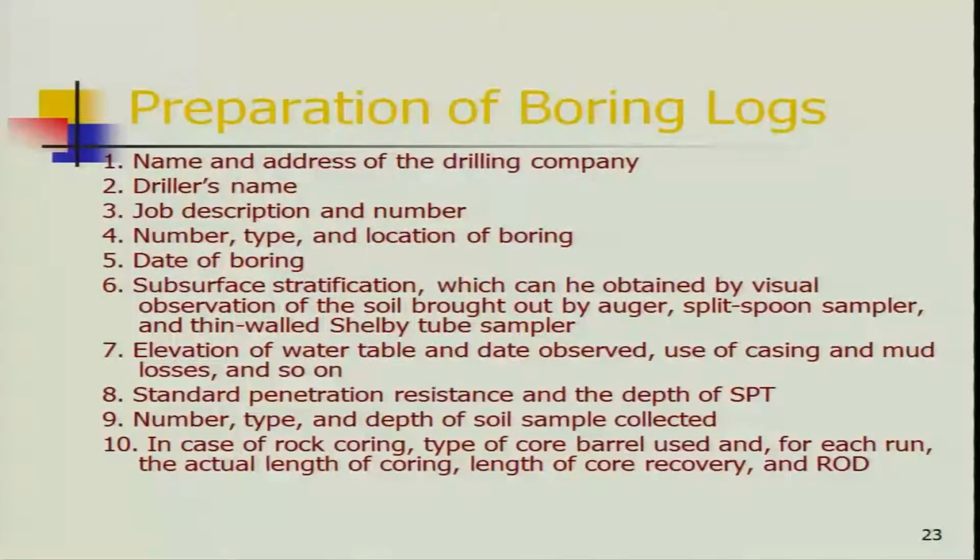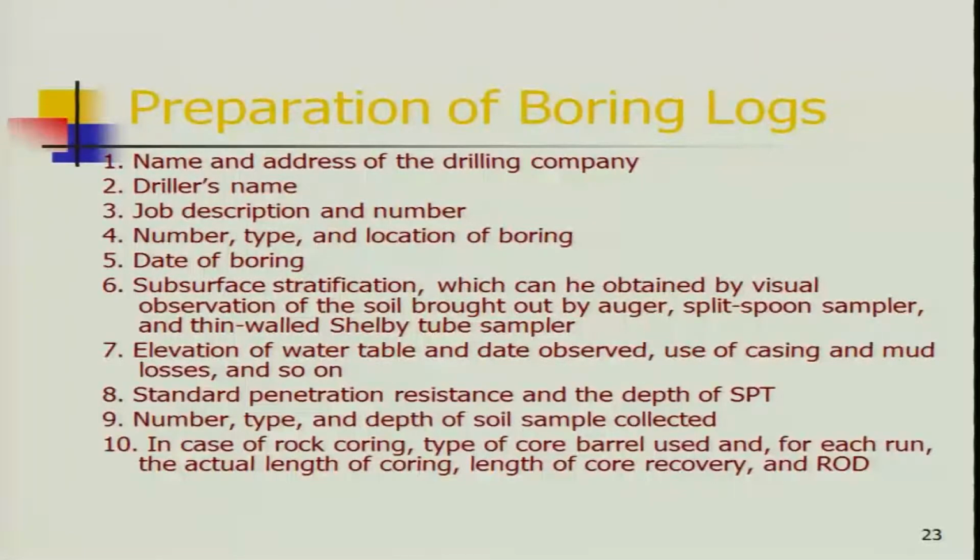So, before preparing your bore log, data bore logs, particularly it will have the name and address of the drilling company or agency who has done the drilling, the driller's name, job descriptions and number, meaning if it is a multi story or multi places you are doing, job 1, job 2, job 3 and number. How many boreholes you are doing, number, type and location of your bore holes, this is most important, number, type and location of your bore holes.